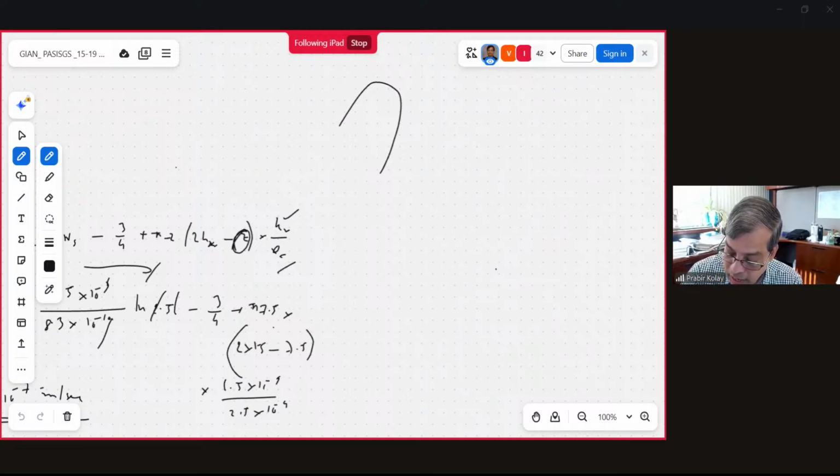As I mentioned, this is a drainage layer. PVD is up to here, not the whole depth. This is the permeability KV1, and this is the permeability KV2. That's the one you need to know. You need to find out the optimum penetration from here to here, H optimum. So this is the equation for that. And this is the drainage layer here, and also here.